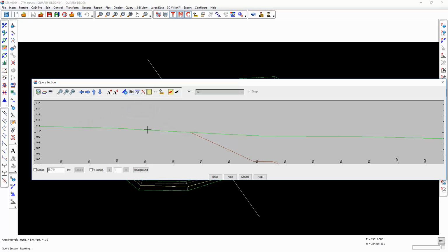In the unlikely event that the ground model rises steeply and my bund ends up in cut by the time it's completed the flat 2.5 meter wide top, then there will be a cut command inside the template in order to cater for that situation.